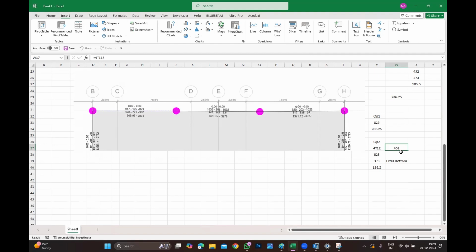So at that particular location, when you check the area of steel, you need to reduce the effective depth and increase the effective cover. But practically, it does not have any impact, even theoretically, because you do have a lot of factor of safety. Someone who wants to punch you will ask you to reduce the effective depth, increase the effective cover, and see the required area of steel. I wanted to keep it more precise, or else it does not affect anything. It's only a localized area.